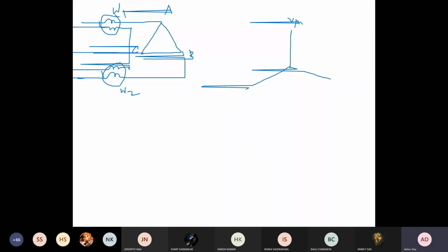Right? So when you do this and your drawing was like this, this is your IAB, and then you should take IAC, which is on this side, and then you get the IA like this. So this is your IA. This angle is theta plus 30. This is 30. This is theta. So between VAB and IA, it is 30 plus theta.